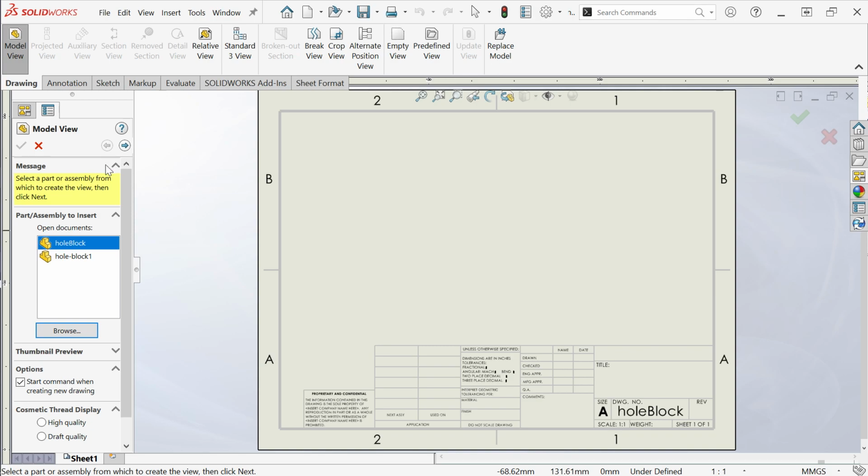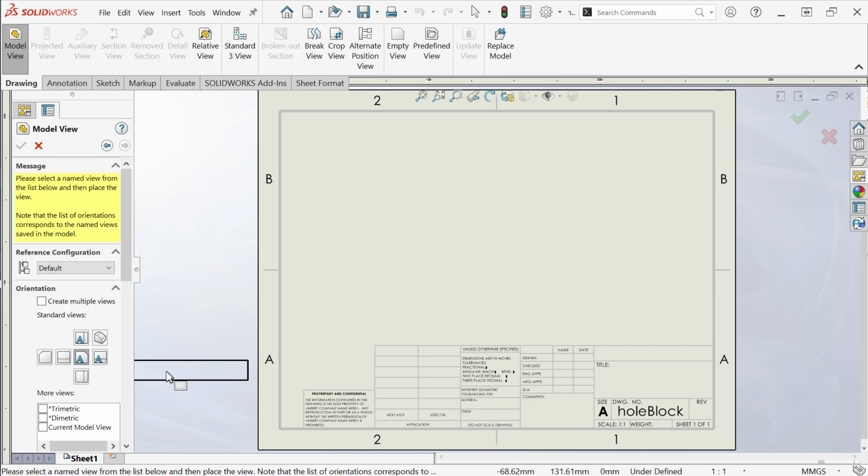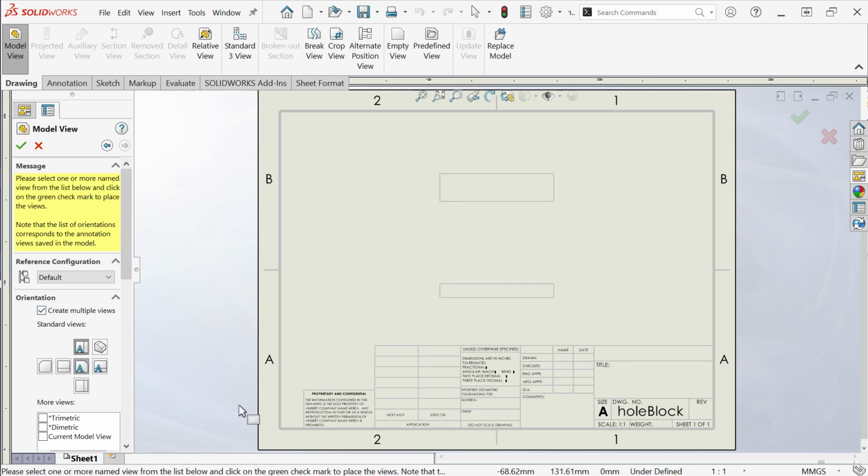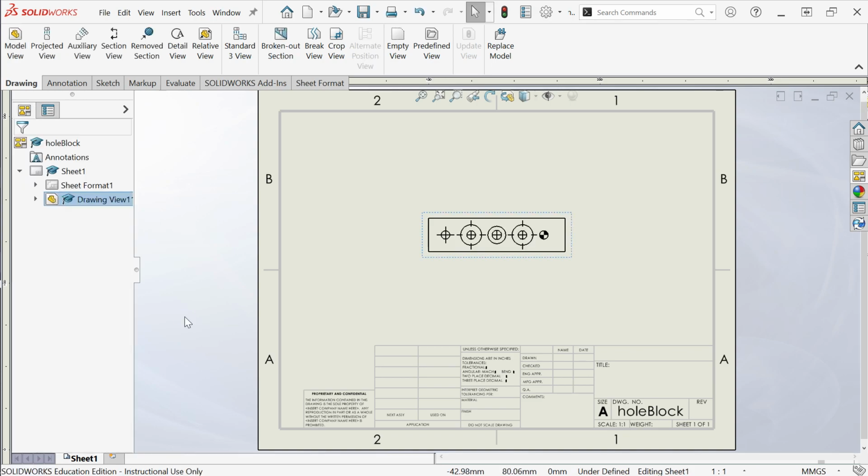So once that's selected, I hit the right button. And you notice that there's not much going on here. This is side view. We certainly could add that. But I want certainly my top view to be added. I don't really need the side view because there's not much going on there. Okay. So then I click somewhere in the drawing area. I should insert that view.